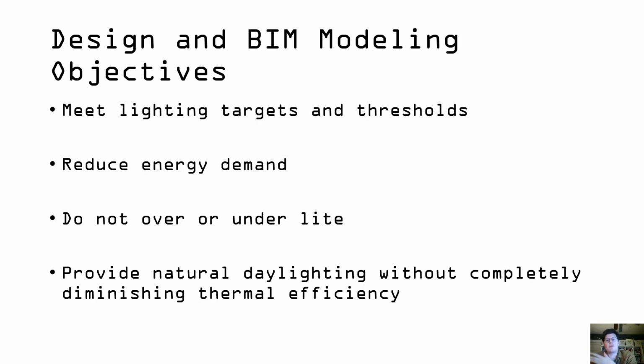Every time we create a window or an opening, we are creating a glazed area within the building shell, which I can almost guarantee is less thermally efficient than a metal stud wall with insulation, a brick wall, or even a concrete wall. Glazing is the least thermally efficient building assembly most of the time.